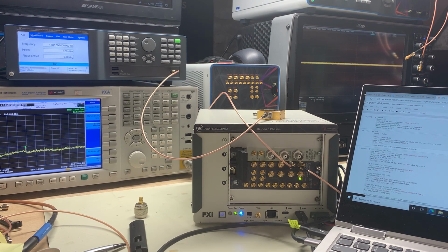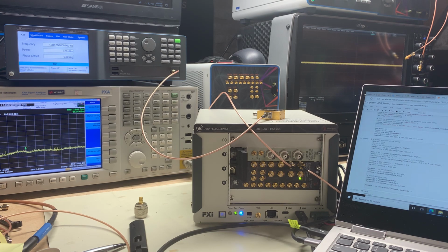The bandwidth on the scope is important because we're going to generate some high frequencies today, and the very wide bandwidth, very wide dynamic range on the spectrum analyzer allows us to measure the spectral purity or the fidelity of the signals that we're going to create today. So first of all, let's generate the signal that we talked about in the slides. A 2048 point, just generated it. Now download it to the instrument.